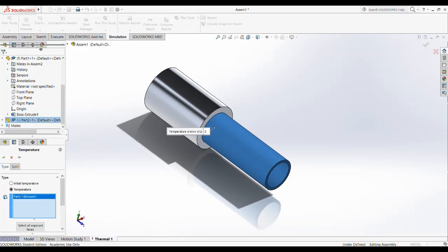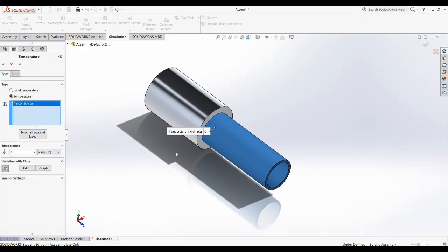and now I'm going to put the window back up, and it's setting us to 0 degrees Kelvin. That's probably okay, but I feel uncomfortable. No, I'm sorry, the initial temperature is supposed to be 220 Celsius. So first I have to change it from Kelvin to Celsius, and then it converted 0 Kelvin to minus 273.15 Celsius. I want 220. That's my initial temperature.